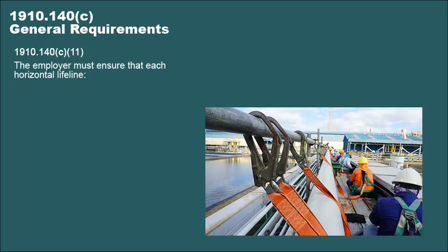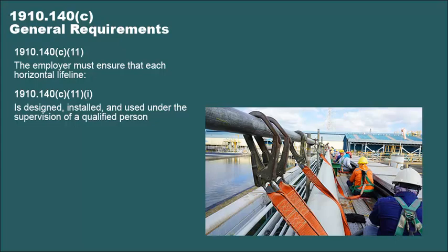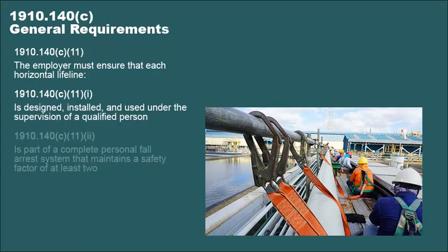1910.140C11 states a horizontal lifeline should be designed, installed, and used under the supervision of a qualified person, designed and installed by the employer, and is part of a complete personal fall arrest system that maintains a safety factor of at least 2.